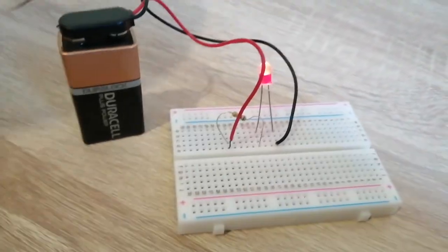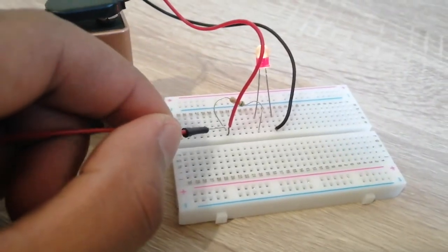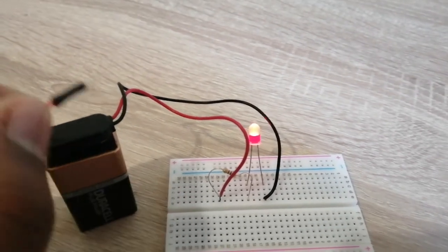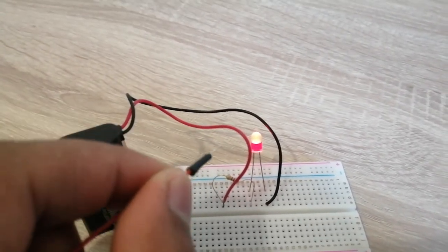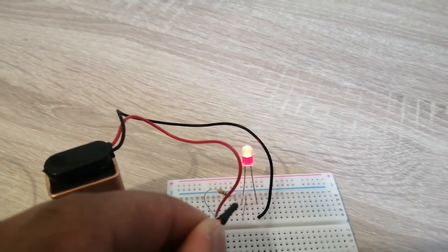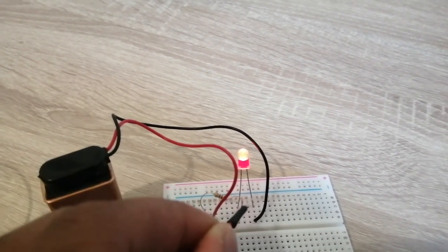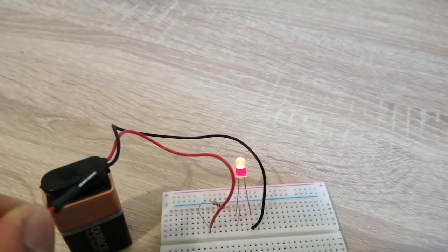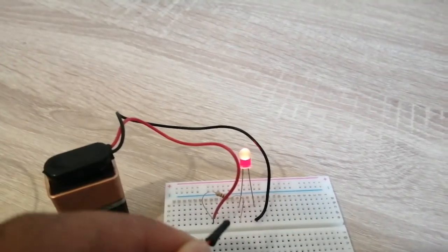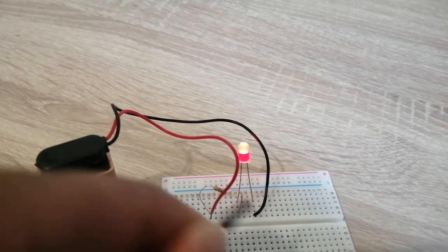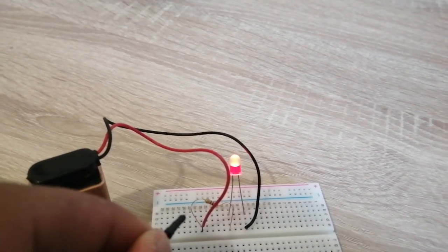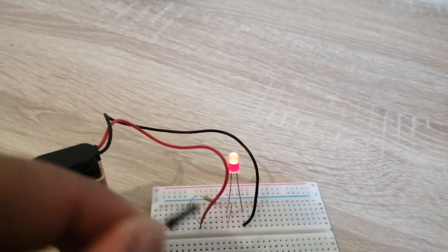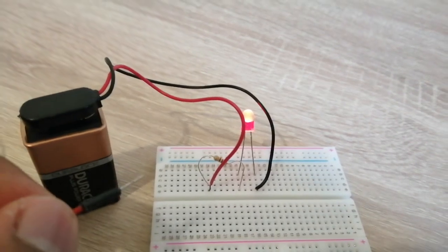So what we have now is we have the power. Here's the LED, it's lighting up. So we have our current flowing from the red one to the resistor, from the resistor all the way up to the black one, and it goes to the negative part of the battery. So that is similar to the circuit that we designed, in that the only difference is that this uses a 560 resistor and the one we designed for is a 550. So that's it, guys. That is a circuit.